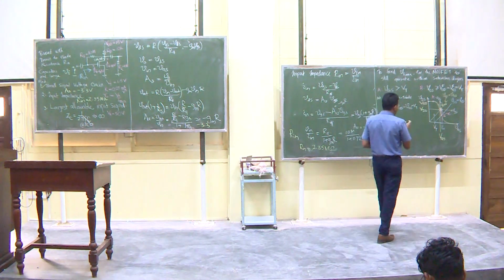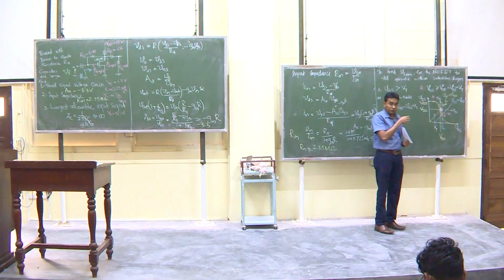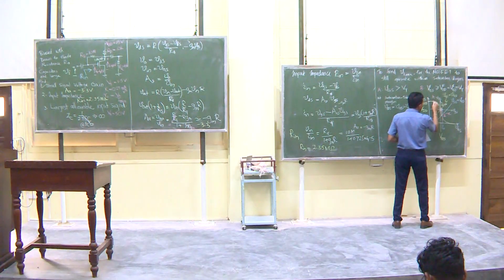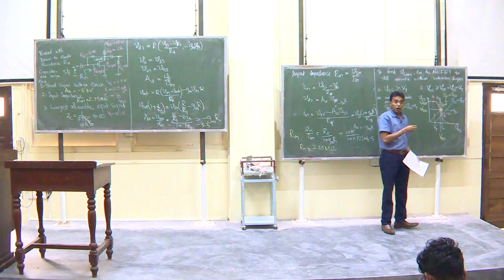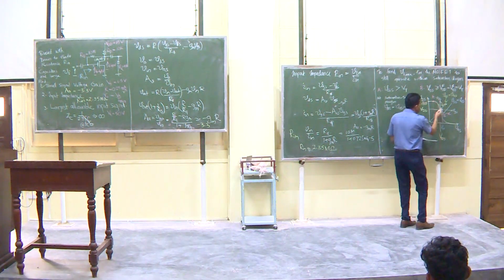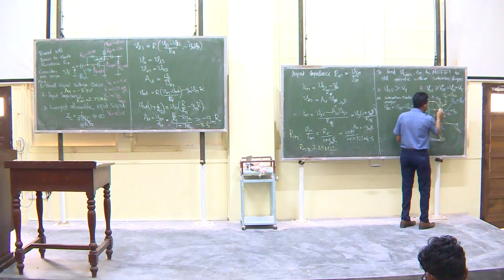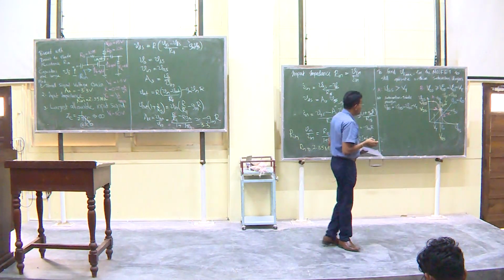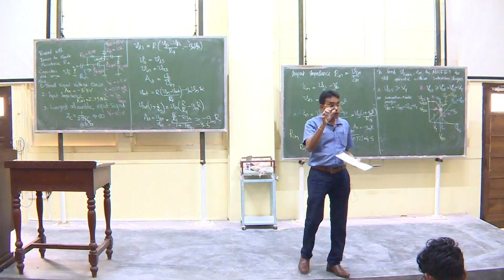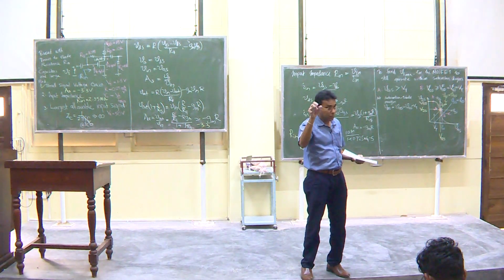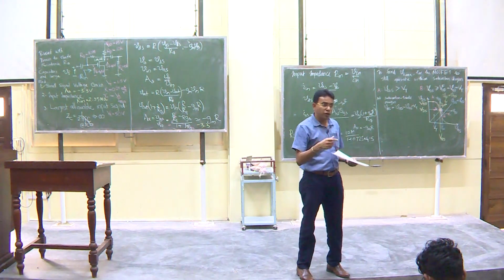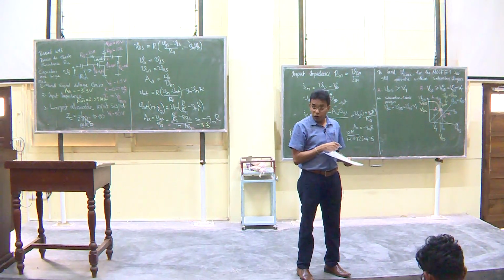On the other side, if I reduce this a little bit, that is also possible. You can reduce it so that it goes into cutoff. Let us call this Z. If Z is bigger, I have to go with X, that is the maximum, otherwise it will go into triode before it goes to cutoff.